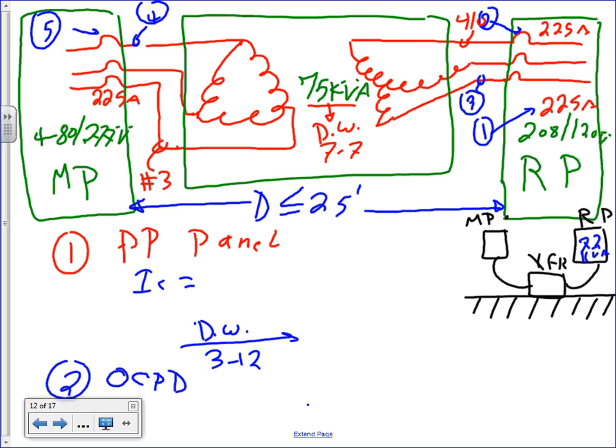If you look at three phase, I want to look at 2.8. So what size transformer can I get? Look at the first column, and look at my derated receptacle size, which is 72. What's my next standard? 75. Do you understand why I came up with a 75 kVA transformer? Everybody understand now? I did the calculation on the receptacle panel, I came up with 72. My next standard is what? 75. Can I have thumbs up?